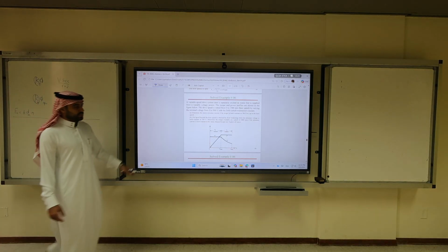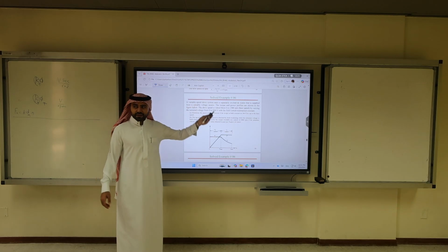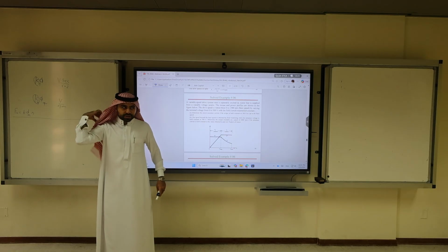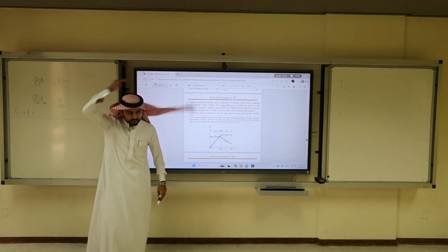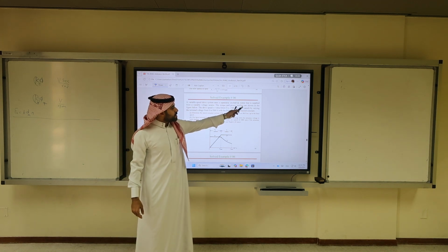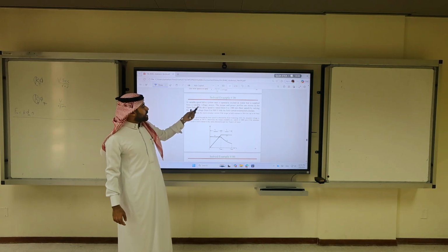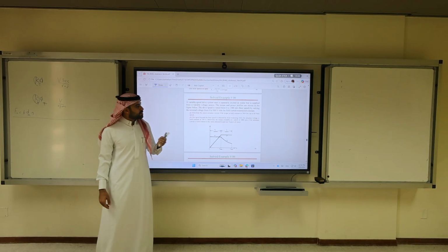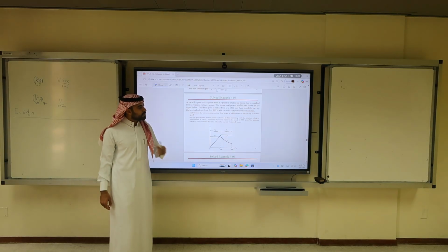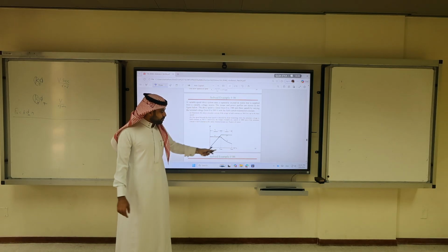Variable speed drive. What is variable speed drive? Variable speed drive is somehow a power electronics. It uses a separately excited DC motor that is supplied from a variable voltage source. So a variable speed drive uses a separately excited DC machine. The torque and power profiles are shown in the figure below.